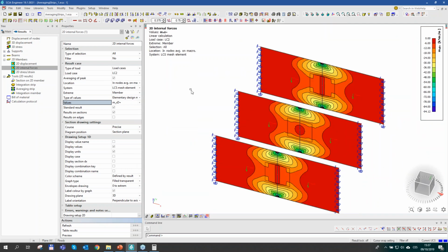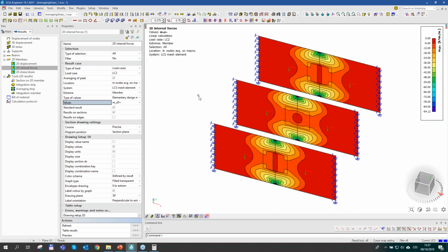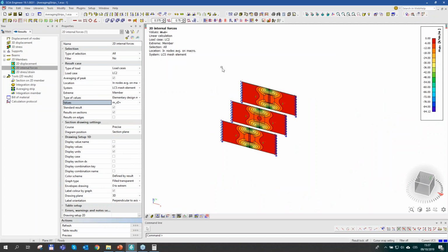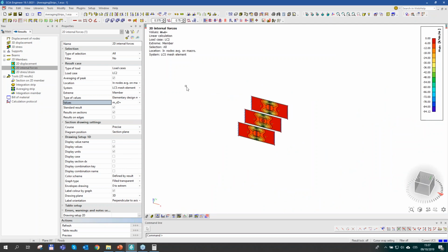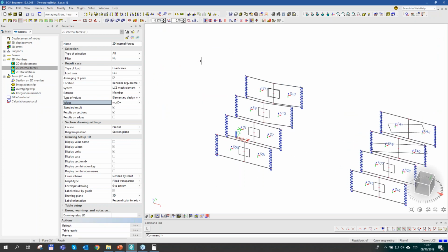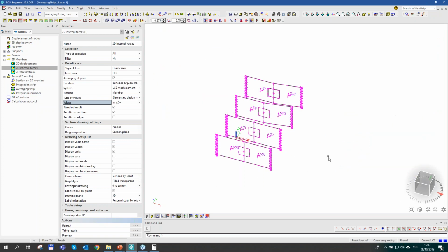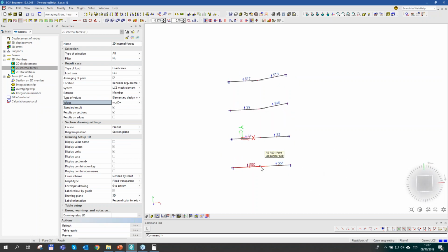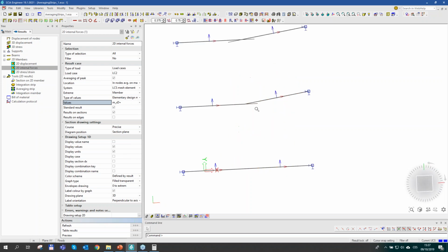And another thing I would like to point out that may sometimes be confusing, why it doesn't work as you would expect, is, and let me again select a proper part of this project, that in fact your structure needs to be perfectly in plane. So I have 4 walls right now.